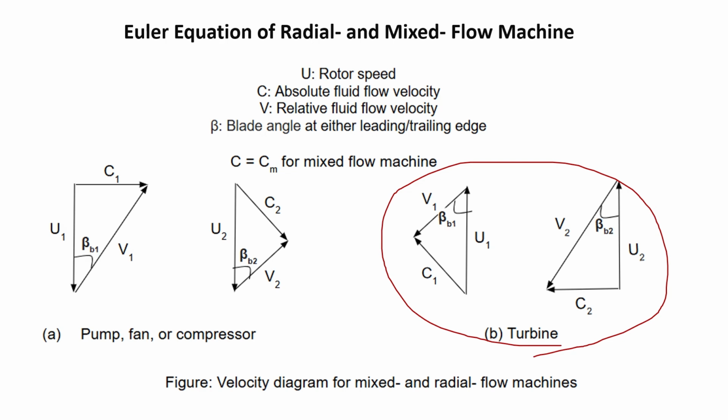But in contrast, at the trailing edge of course you have swirl flow at the outlet, or otherwise this will not be called a power consuming machine, because you want to maximize the tangential component.